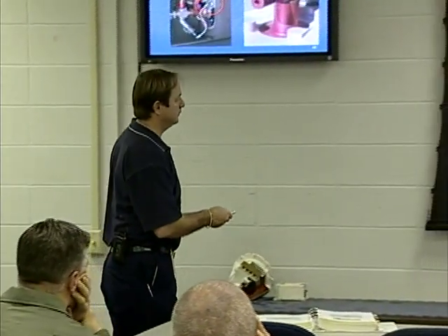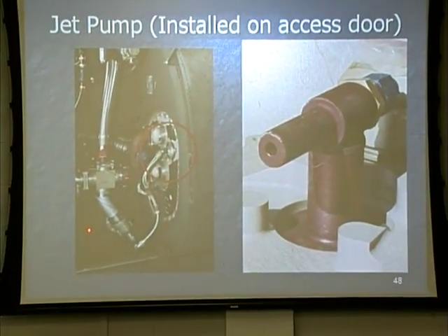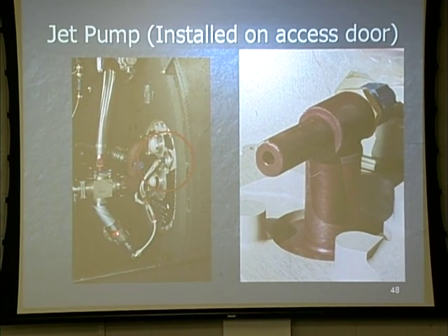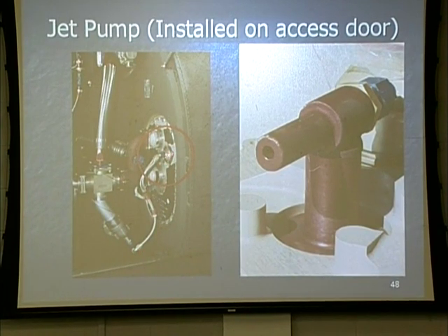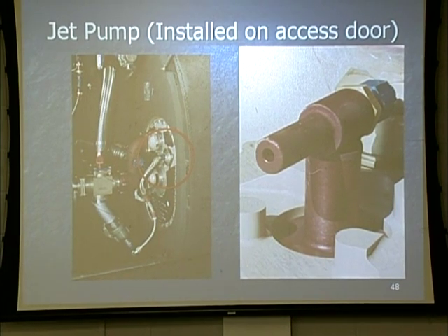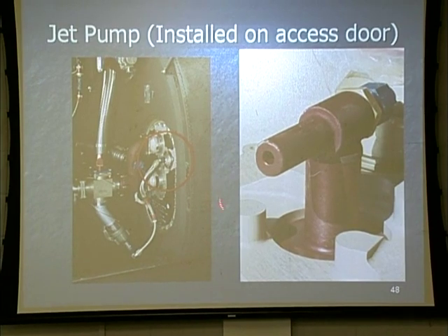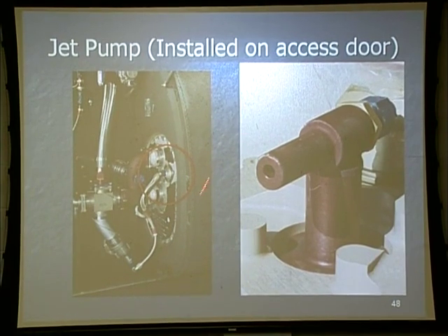This is your line between that pressure refueling line that runs underneath the forward inner tank area. There's a line on the back of it that's going to go up and associated with the forward main pump on each side. So there's actually 2 of these jet pumps. This is inside the tank itself. Everyone tracking where we're at? And you'll notice it's at the front of the tank. Again, we're talking the forward inner tank area.